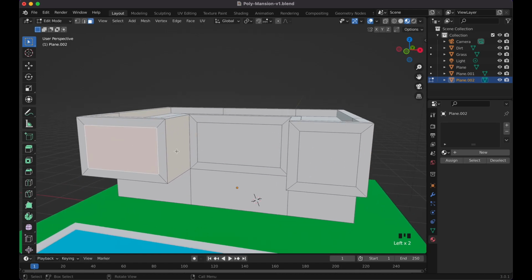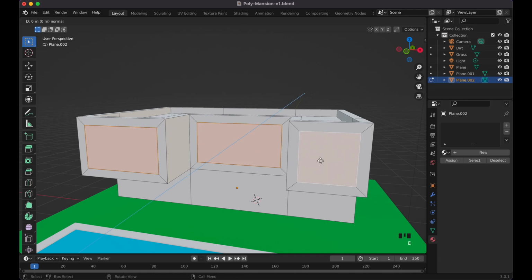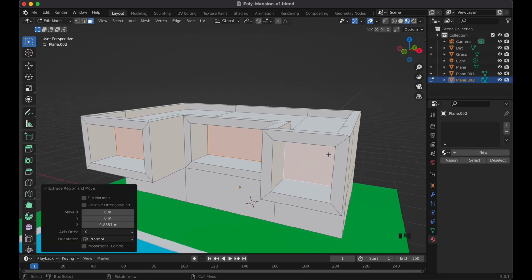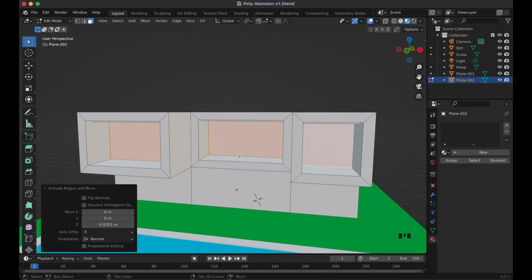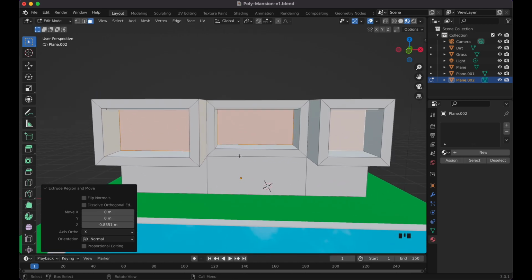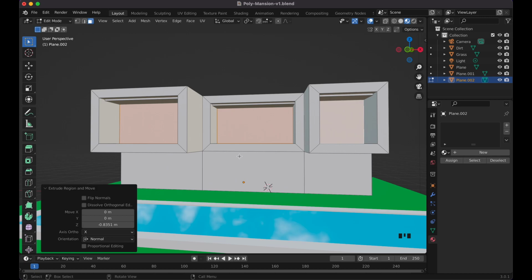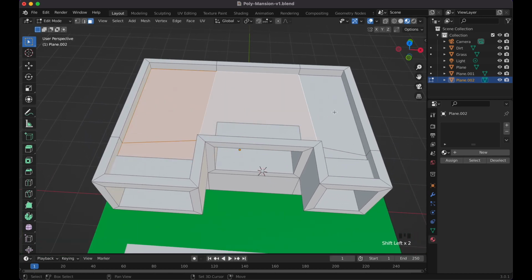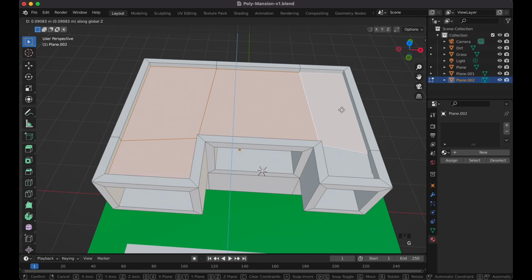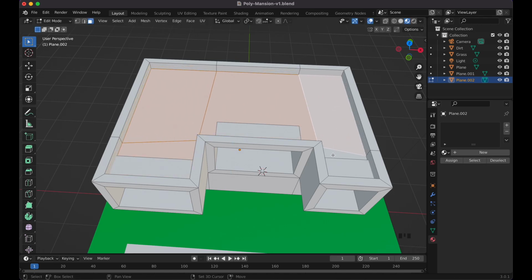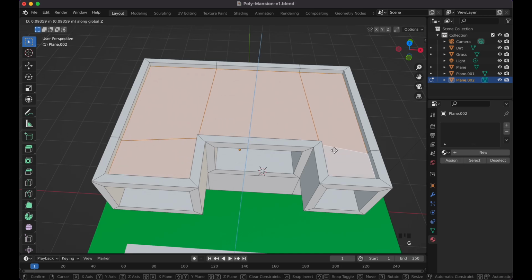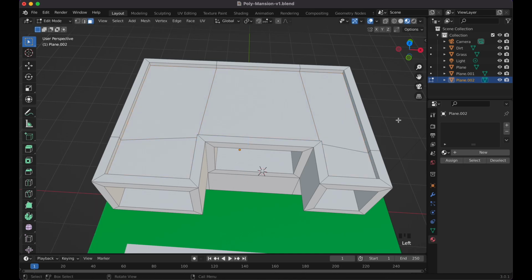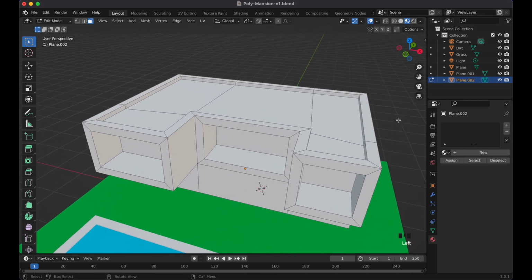And then what we could do is click on all these faces, 1, hold Shift, click on this one, press the E key to extrude it, and then we can just bring it back, let's do it right here. And then I just realized that the top is going a little too low, so let's just do this, G Z, and just bring it up. Oh, I forgot to credit this one too. G and then Z, and there's like that. And now it looks much better here.